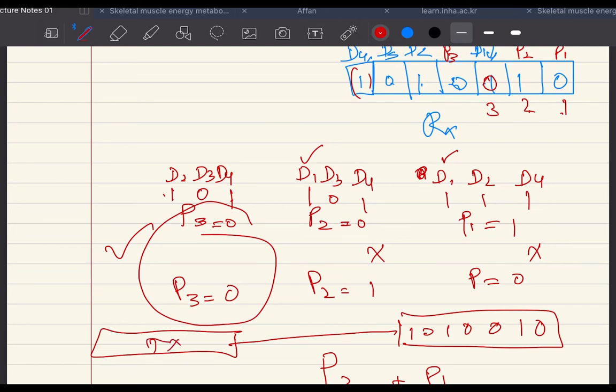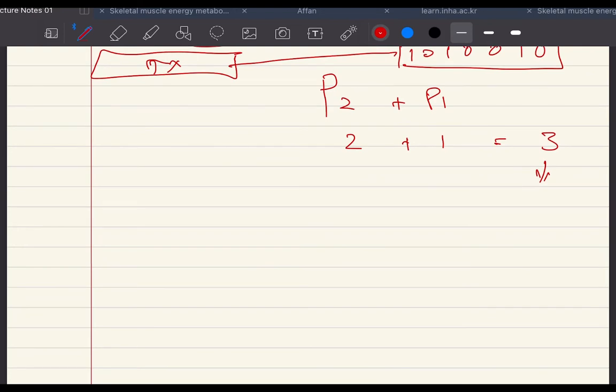Now, this is very clear. Please remember that the drawback of Hamming coding is that it can only correct up to 1 bit. So it cannot correct more than 1 bit per sequence. For each block, it can only correct up to 1 bit. If 2 bits are corrupted, then Hamming coding cannot correct them. There are more sophisticated coding techniques, like convolutional coding or turbo coding. They are very robust, and 4G actually uses these robust coding schemes.